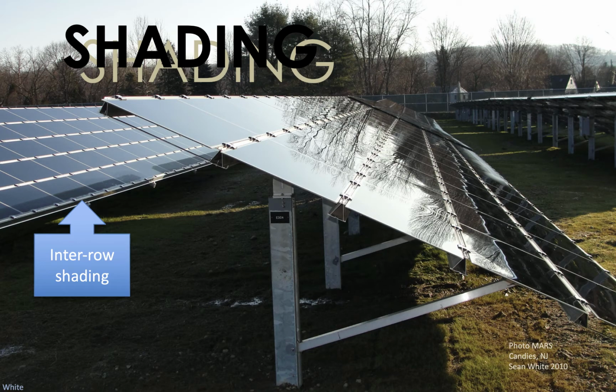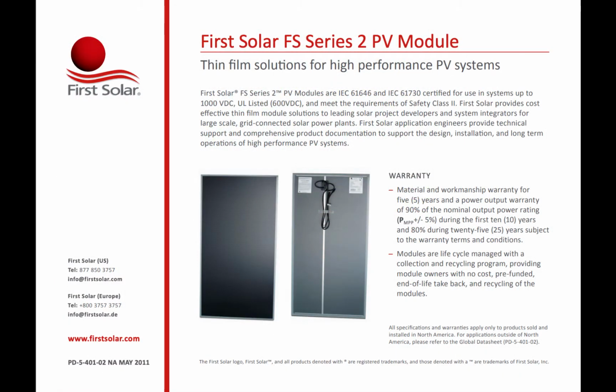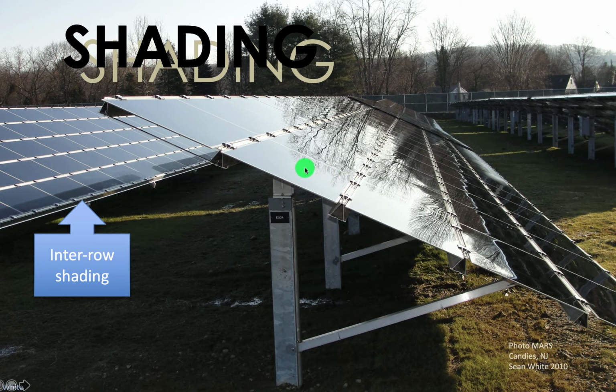This is a picture right here that I took of a PV array in New Jersey. We call this Mars, New Jersey, because it's the M&M's people, the Mars Candy Bars crew. This particular array is a First Solar array, so this is thin film. It doesn't have those regular square or square with rounded corner solar cells. It has many thin stripes, and they put these thin stripes up and down like this. So with this type of solar module, you can shade the bottom of it, and it actually is proportional. So this shadow is not as bad with a thin film array as it would be with crystalline silicon solar.